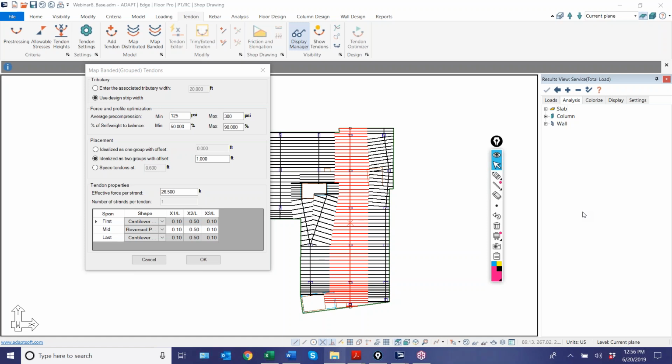If you add more PT for that design, you'll get less reinforcement for crack control because the post-tensioning is controlling the stress, which might indicate where it's cracked. Those are directly related. So for ACI, usually you meet the minimum P over A both in the banded and in the uniform directions. All right, so just looking to see if there's a follow-up question there. I think we're okay. All right, so we enter our inputs for pre-compression and percent self-weight to balance.